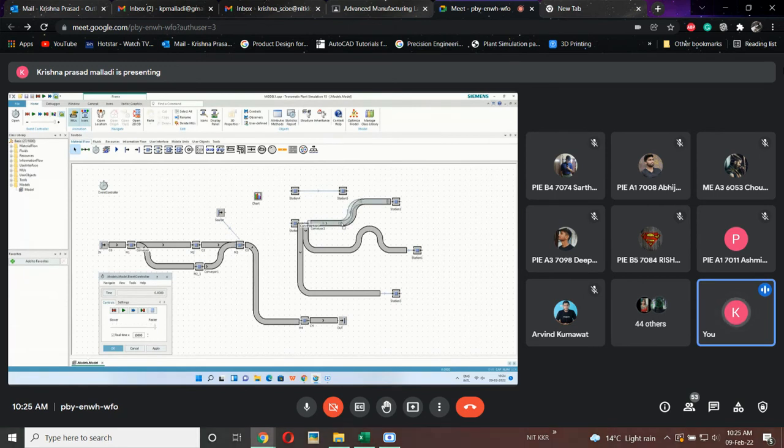Conveyor can be used for two different things. One is for a smoother material handling rate, so that the material will travel from one station to the other in a smoother way, and it will be clearly visible. And the second thing is to reduce the blocking. That is one of the main reasons we use conveyors in industry. With using the conveyors, what exactly happens? The bottleneck between these two stations, the blocking phase, will definitely be reduced.